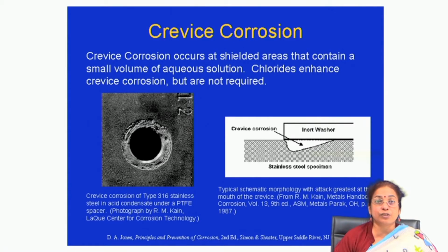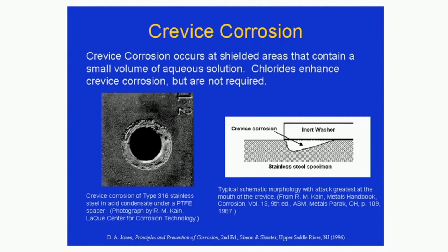As a result, the corrosion rate of the inner region is much higher and goes on proceeding to a large extent as compared to the outer region, particularly because of the differential aeration cell formation. This case is further aggravated if there is chloride in the environment, because chloride breaks down the oxide film. Not only that, chloride actually increases the corrosion rate to a large extent.